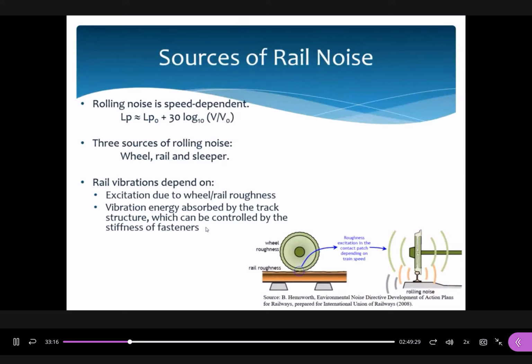This is the first type, the directly fixed type. It means that we just put our wheels, two wheels, on the structure. This is the simple type. And the second one is the ballast type. You can see that for this ballast type, there are many stones that can be used to support these structures. Another point is that for low-speed trains, the provision of these stones can help to reduce some portions of noise effects because there are air gaps between the stone particles. With the presence of these stone particles, it can help to absorb or trap the noise effects. But this is just for low-speed trains only.